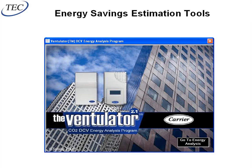We do have software tools available to help you calculate energy savings. This one is a Carrier software tool. It's actually run by Telair, which is the sensor manufacturer for Carrier. There's another one from Honeywell that we use quite a bit as well. The one from Carrier is pretty nice because it gets pretty detailed, and you can model things pretty detailed. The Honeywell one's nice because it not only looks at CO2 but also gives you payback figures for thermostats, programmable thermostats, and economizers as well. So we use both of those depending on what the project's like.